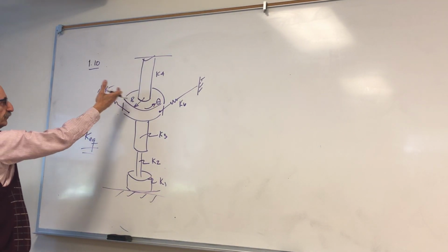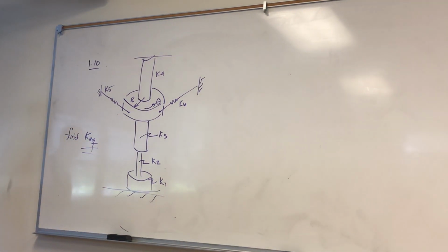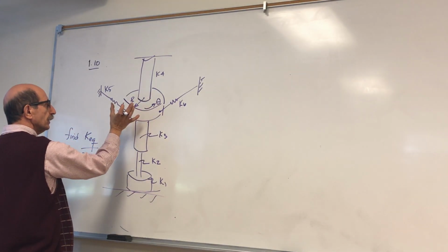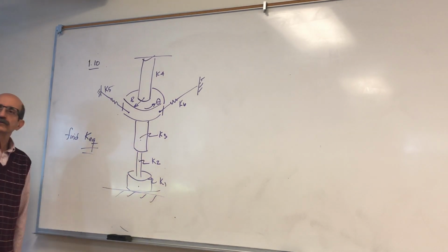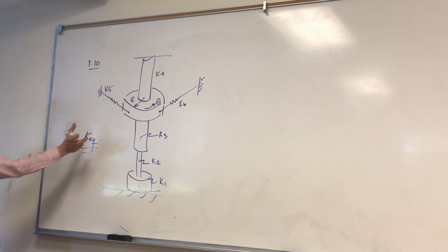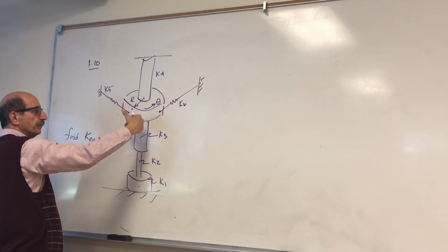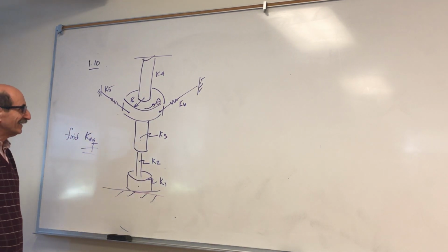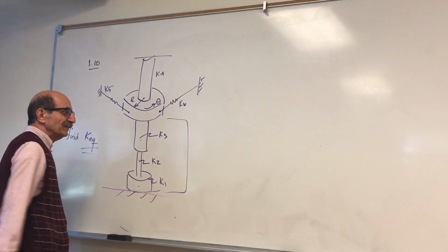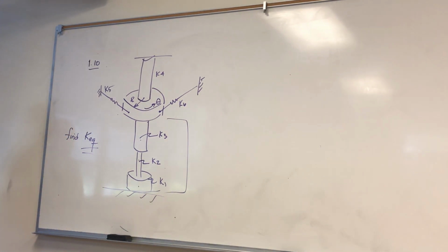Because you have the mass here, you have the moment of inertia, you can set up the natural frequency as long as you find the equivalent stiffness. See, look at this. If this is turning, okay, all you can say is that these three will be subjected to the same force. Imagine if you apply a torque here, right? These three will experience the same force. Well, let's go step by step. You can say that these three are subject to the same force, right?